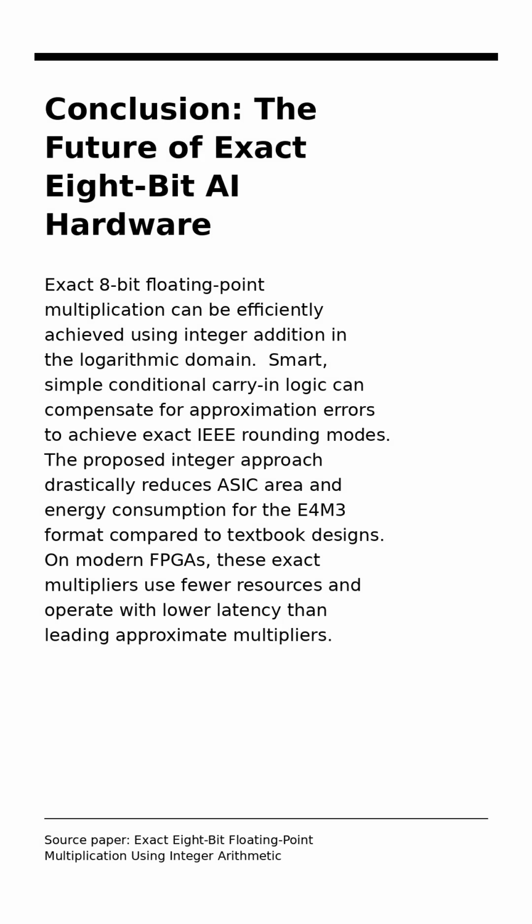By shifting 8-bit floating point multiplication into the logarithmic domain, this research proves we can achieve mathematically exact results using simple integer addition. Using smart conditional carry-in logic to fix approximation errors, the proposed architecture drastically shrinks silicon area, lowers energy consumption, and reduces FPGA latency compared to traditional designs. While the E4M3 format's mathematical limits prevent directed rounding towards infinity, the overarching achievement remains profound. This approach matches the hardware footprint of approximate multipliers while guaranteeing exact rounding, paving the way for radically leaner AI accelerators.